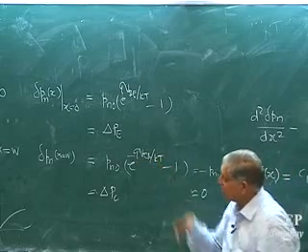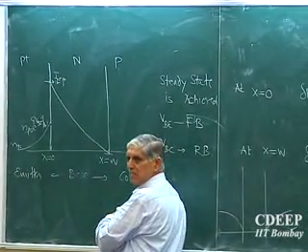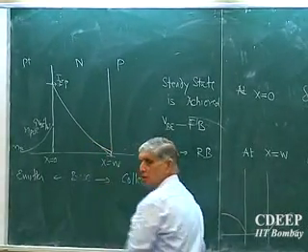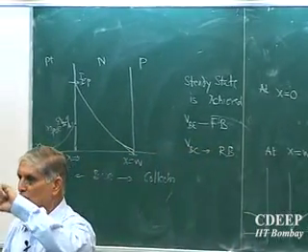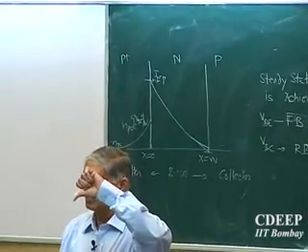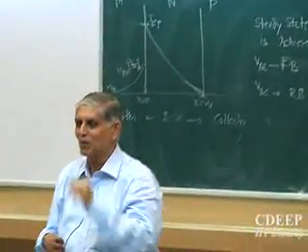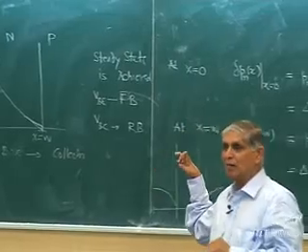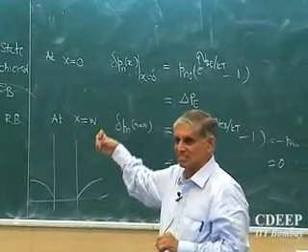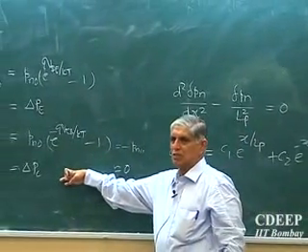So if I do that, where will this point go then? This is minus Pno, where will it terminate then? At x is equal to W, the net carrier concentration there becomes 0, or the excess is also 0 because we say Pno is very small. This is an approximation which will help us to do a lot of good things faster. But if you don't keep it, there is nothing absurd about keeping this delta PC.